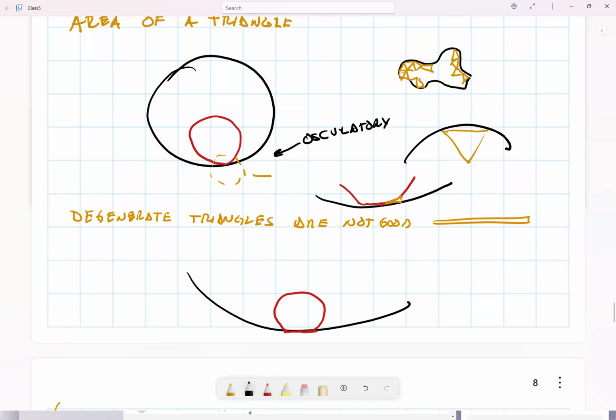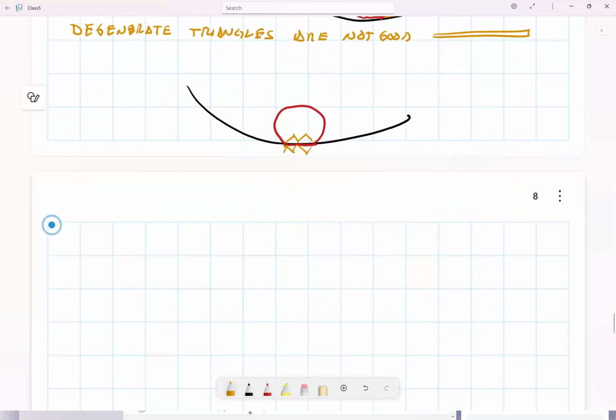But that wouldn't happen. If this is a cable, it has some weight and it has materials that deform. So there will be a flat region at the bottom. It will not be a contact in a single point. So make it like that. And then your triangles have no problem, on both sides. Other people deal differently. They deal with different types of elements. But this is the way that I solve these things, not too much of a problem.